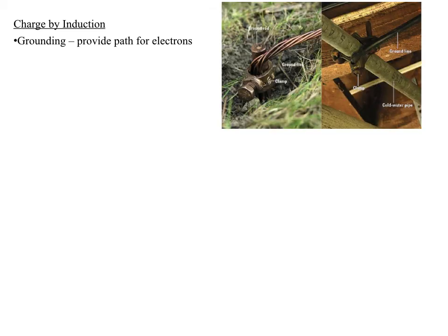As I mentioned, if you look outside your home, you may see something like this. Probably close to where your electrical box comes into your home, you will see a nice shiny copper wire that is connected to a post that goes into the ground. This would be an example of where the wire is attached to a water pipe in the basement or something like that. It's usually connected to a cold water pipe, and the water pipe then runs outside. But so many homes have plastic plumbing anymore that things are grounded individually in the house with wires. We used to ground everything onto the plumbing, and now instead we use wires because so much of the plumbing in homes is plastic now.